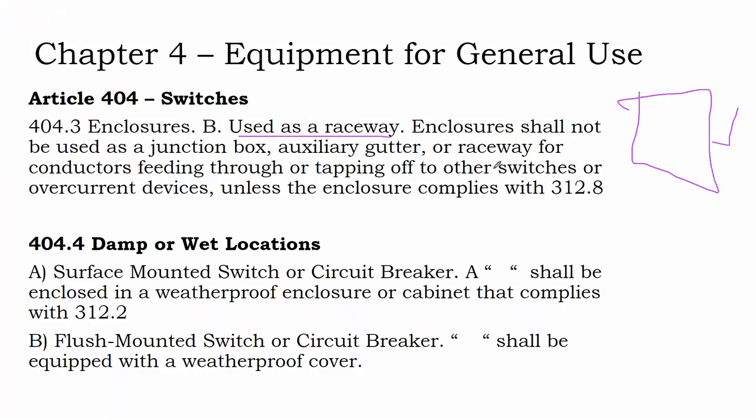Can you use switches as a raceway? It says enclosures should not be used as a junction box or a gutter or a raceway for conductors feeding through or tapping off to other switches unless the enclosure complies with a certain section. We already covered this section. That's the section where it's talking about 40% full with conductors or 75% full with other stuff. So you are allowed to put a tap connection inside a box, inside a meter can, inside a device, but not if it fills up more than 75% of the surface area.